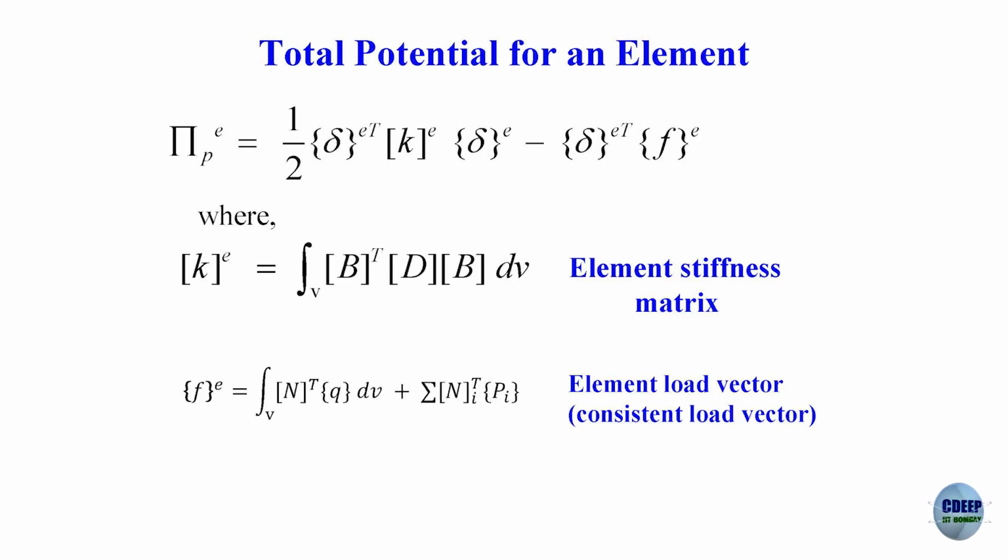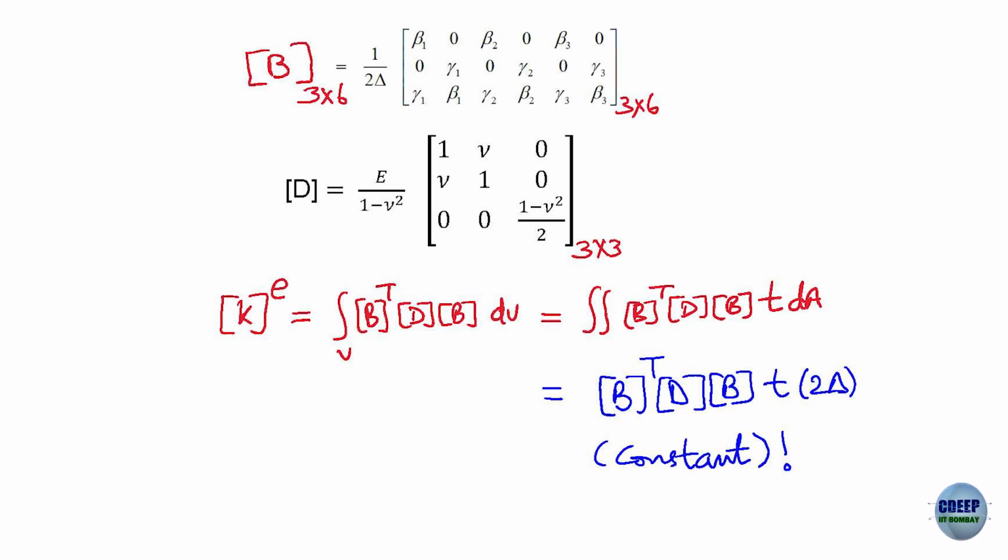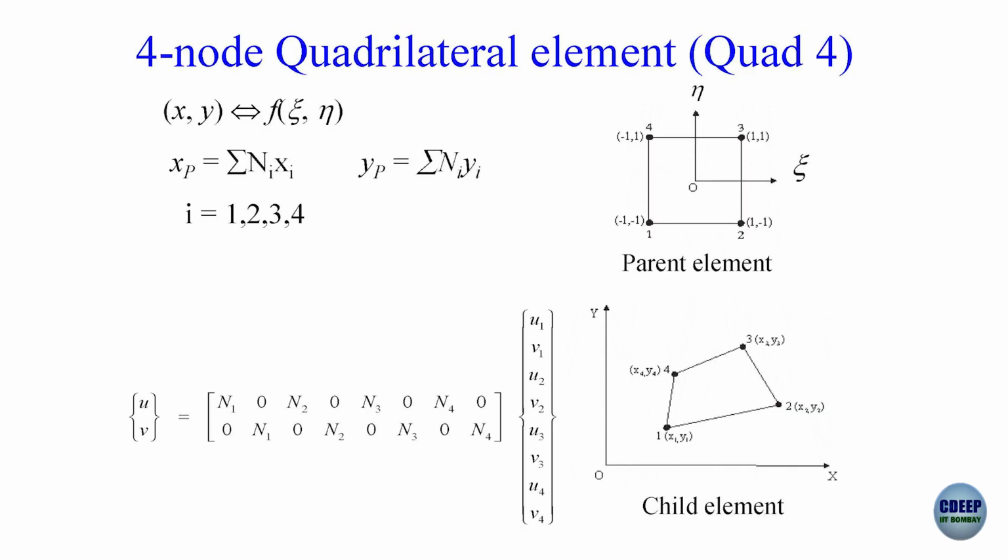Is that okay? So, we used it to formulate the element stiffness matrix for a 3-node triangle, but because it is a very simple element involving linear interpolation functions, the strain displacement was a constant B. So, we need not really worry about integration, we directly wrote down the expression. But now, I will go to the next element using essentially the same expressions.